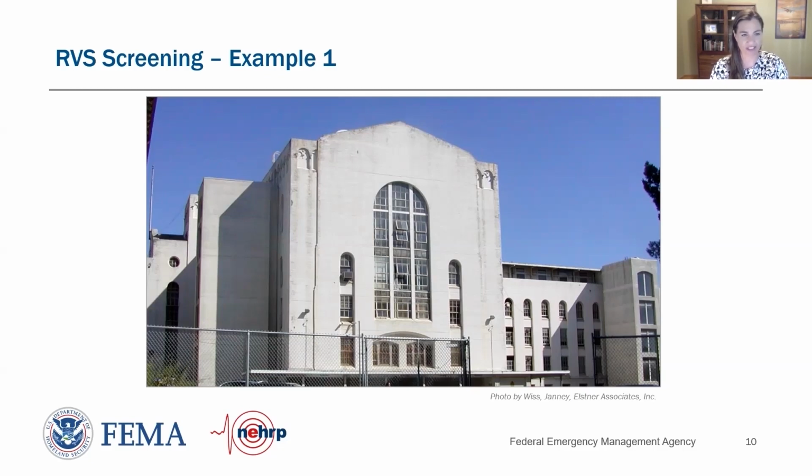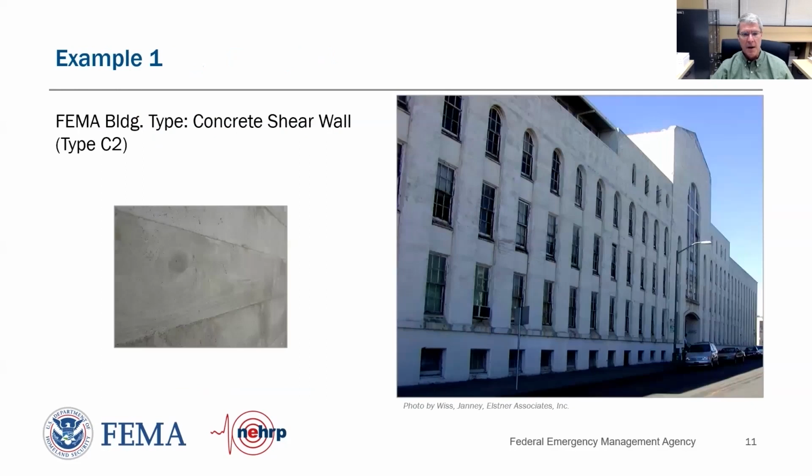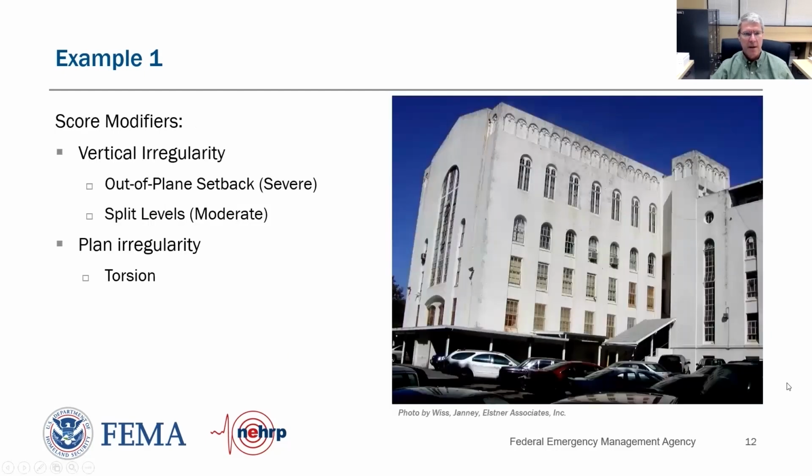It looks more like a shear wall. Exactly, so that's what we're left with, which is C2. And in fact, if we were to walk up and more thoroughly look at the exterior surface, we would see the planking used for formwork for this building, which suggests strongly that this is a concrete shear wall building type C2. So yes, very good.